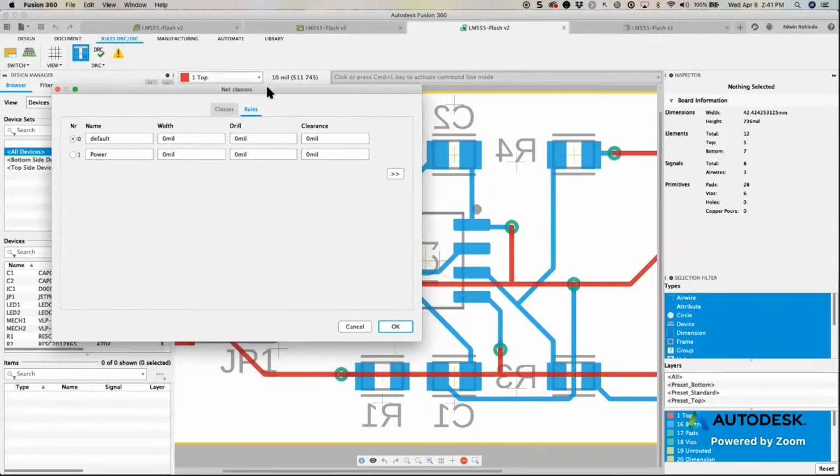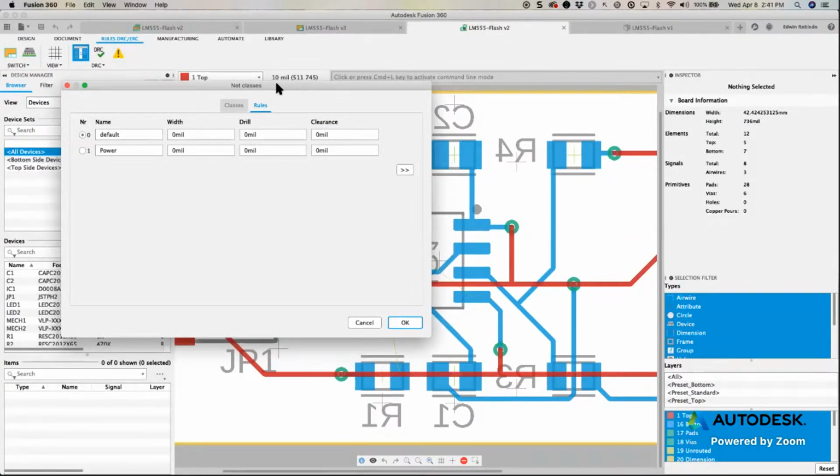Okay, and that's something that comes up with the net classes, because sometimes we see users who try to specify a width that's smaller than what the DRC is specifying, and that doesn't make any sense. And it keeps on bumping it, and they don't understand why it keeps on bumping it to the minimum. So they need to either set up a net class, as I'm going to show you now, or go into DRC and change that minimum value.